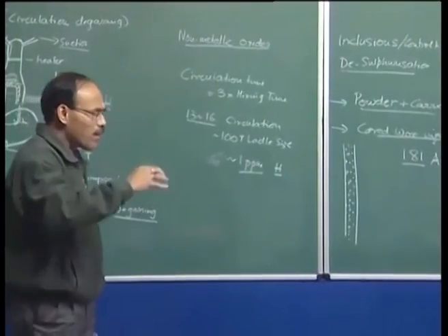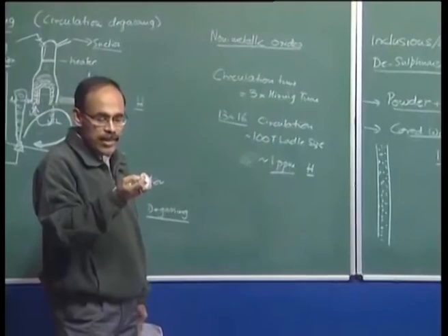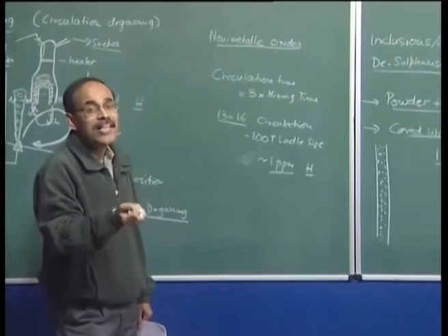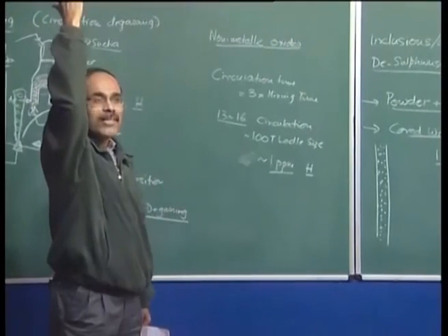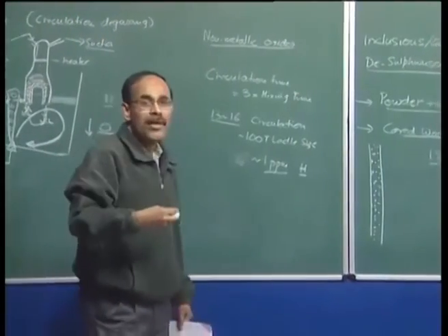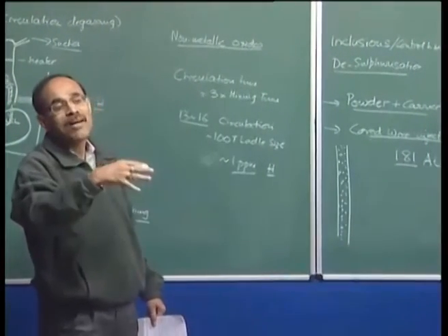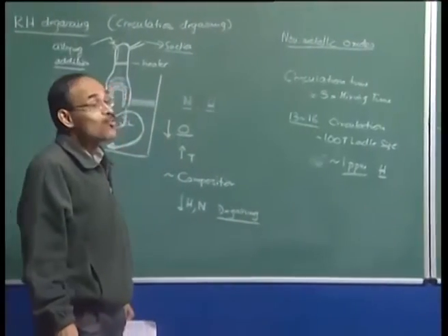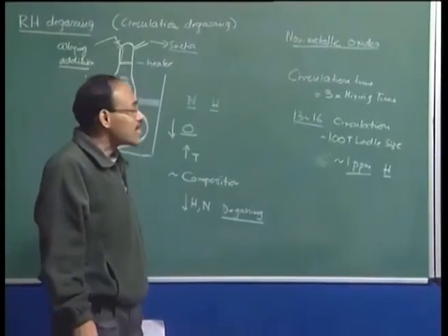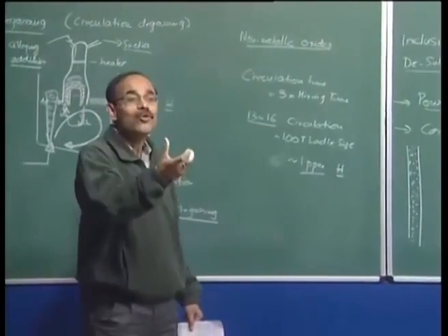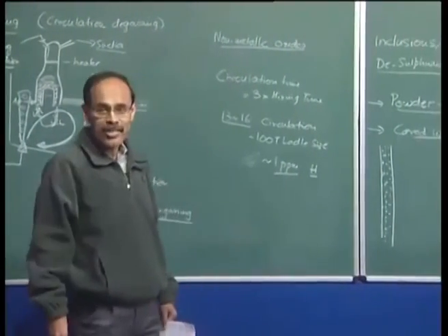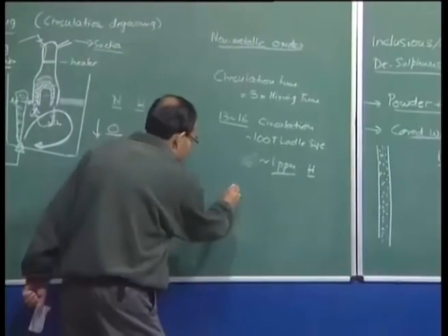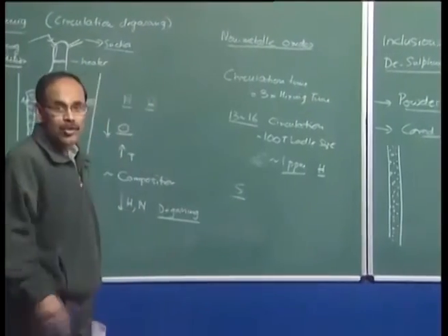The vapors being lighter will immediately try to come out of the melt itself, and the contact time between calcium and molten steel is going to be extremely small, and as a result you will not be able to dissolve a significant part of calcium, because if sulfur is sitting in the melt in the dissolved form, you want calcium to react with this sulfur.